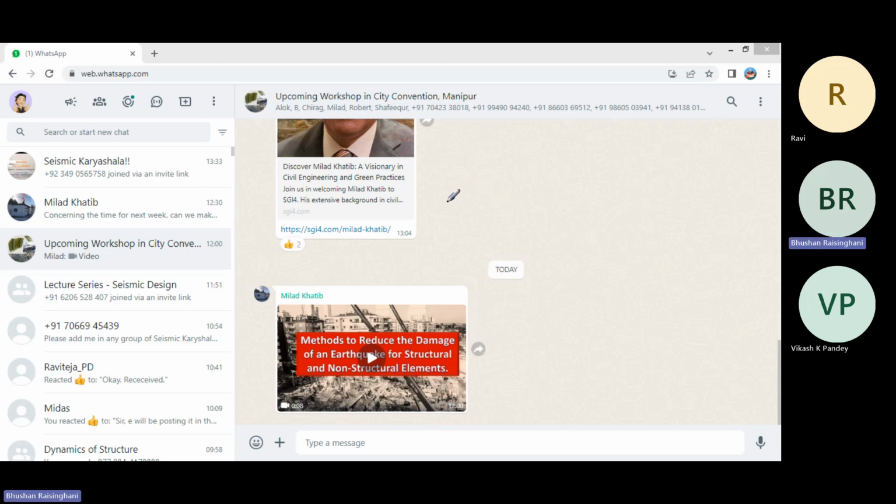In the horizontal direction, you should have that development length. So 50% of vertical on both sides, 50% of horizontal on top and bottom. This way the opening of the shear wall has to be detailed story wise. The horizontal bar should be provided with development length in tension beyond the edge of the opening. So this will have Ld.